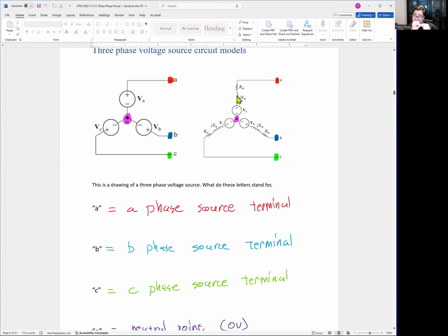Also, because you have thousands of feet of wire inside a generator, the 1,000+ feet of wire will eventually add up. You'll have some internal resistance in the generator too. So if I want to be really, really real-life accurate to the 10th degree, you will have to put your resistance and inductance in series with your voltage source to represent a physical generator.